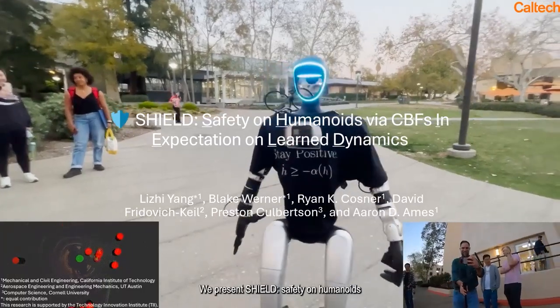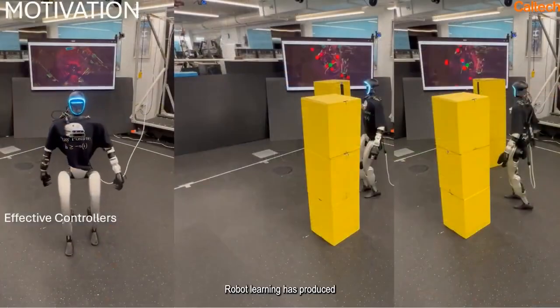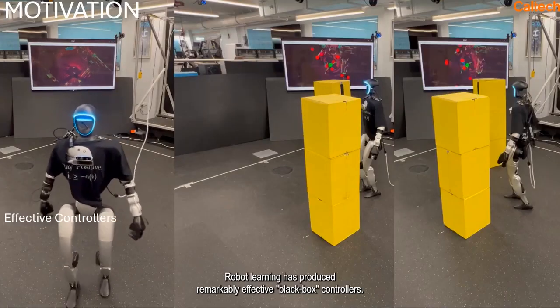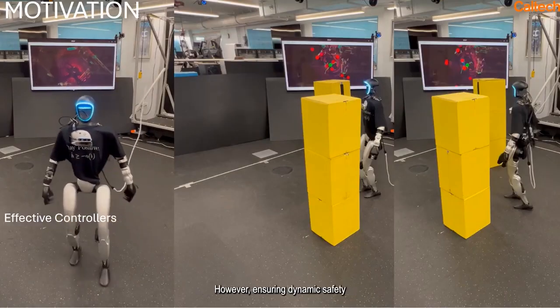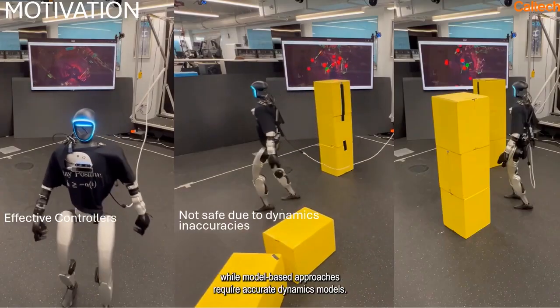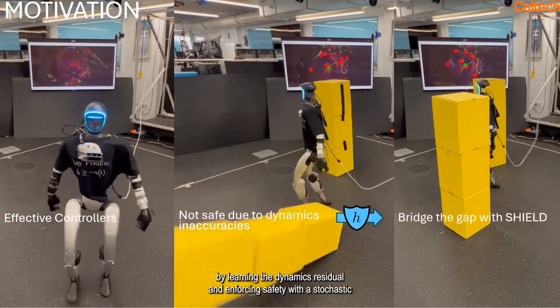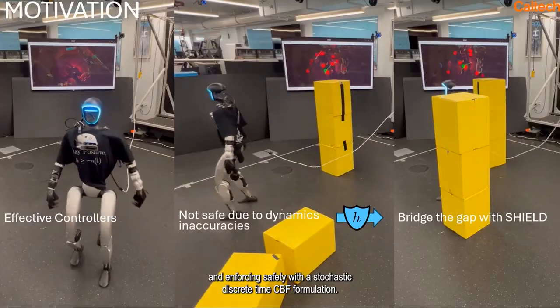We present SHIELD, safety on humanoids via CBFs in expectation on learned dynamics. Robot learning has produced remarkably effective black box controllers. However, ensuring dynamic safety remains challenging. RL embeds constraints heuristically while model-based approaches require an accurate dynamics model. SHIELD bridges the gap by learning the dynamics residual and enforcing safety with a stochastic discrete-time CBF formulation.